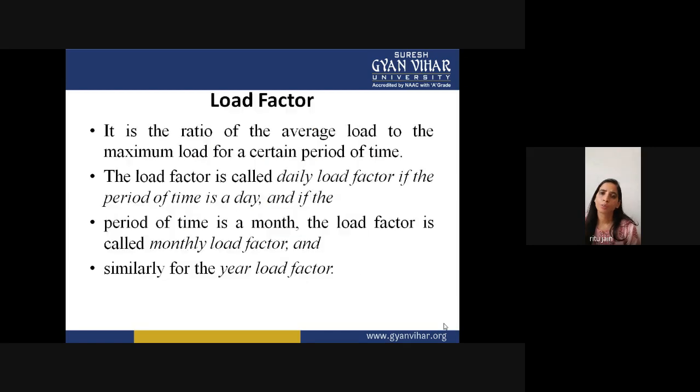Next, we come to the point load factor, which is a very important topic. And what is load factor? It is the ratio of average load to the maximum load for a certain period of time. This is your load factor.